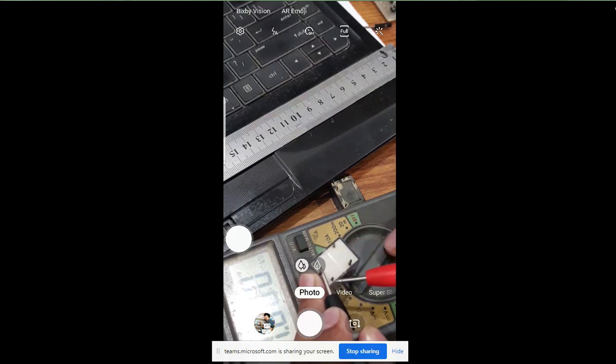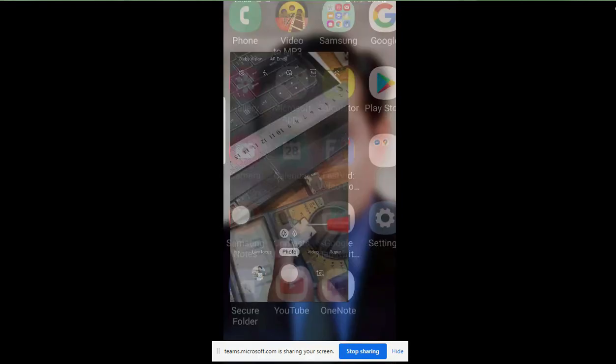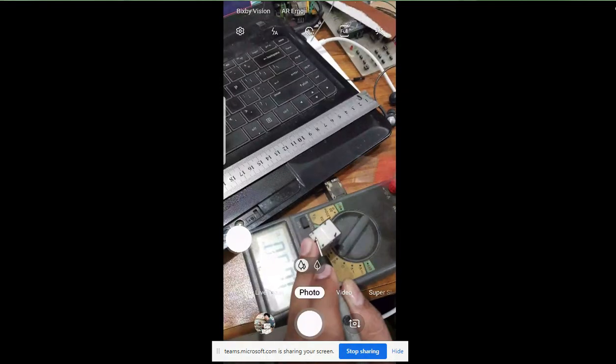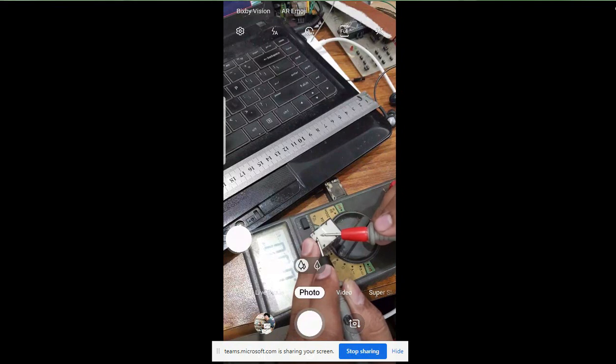So if you want to turn a fan on over here, what you will do is give 12 volts over here, and you will give the fan contact at this point, and you will have the 220 volt live wire coming over here at this point. So this is a relay over here.